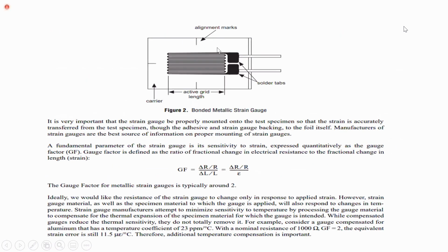See here, students, we have a fine wire, and this is one kind of strain gauge, and the other one is where we frame coils as a grid. The basic point is that this should be a resistive material, and here we should have cables. These two cables we have to connect to a circuit, and then we apply force on this grid, on this fine wire.